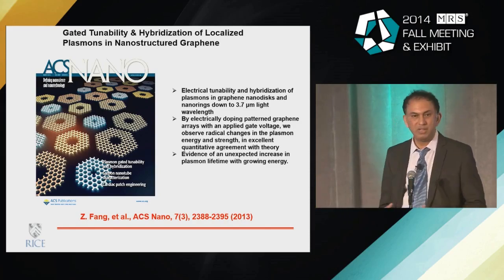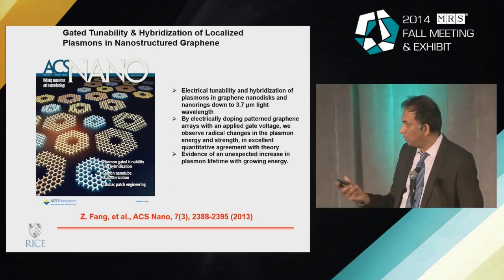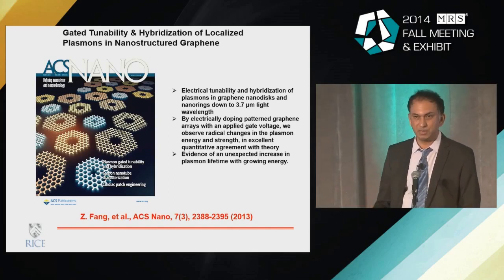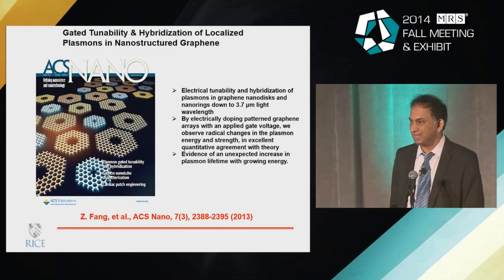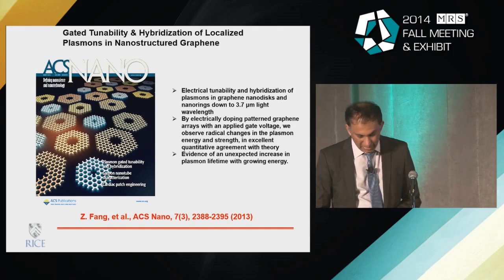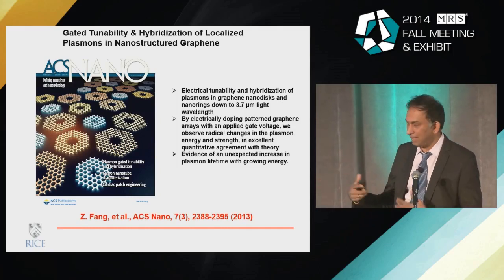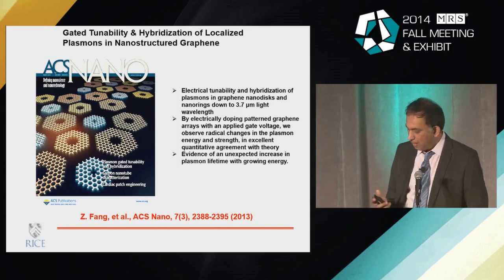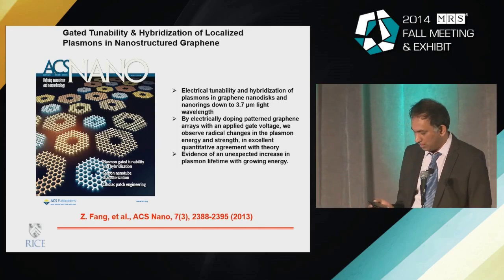Now, bringing the size down or nanostructuring these graphene type material, but in addition to that, also electrically gating, which is equivalent to some kind of doping process, you can also introduce some band gap. And by doing that, you can even increase the absorption of light that passes through. So by really playing around with the size and the gating, you can really change the absorption of light. Again, this is to do with the plasmonic manipulation. You can actually control some of these absorption.